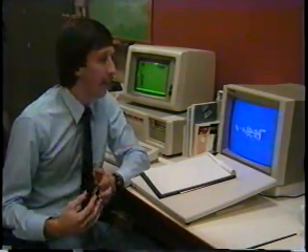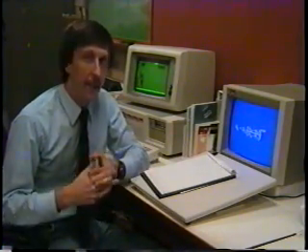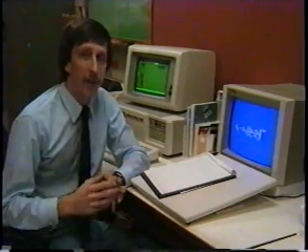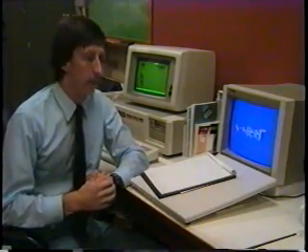And with that model, you can now play these what-if games. What if the fire happens when the pumps are off due to a power outage? What if the fire happens if the tanks are empty or very low for some day? You can't really do this out in the physical world because you'd be interrupting someone's services. But by getting the data from the field and then taking it back and combining it with the capabilities of a computer model, you can do so much more than you can with just the results of the test, as we used to be able to do in the old days only.